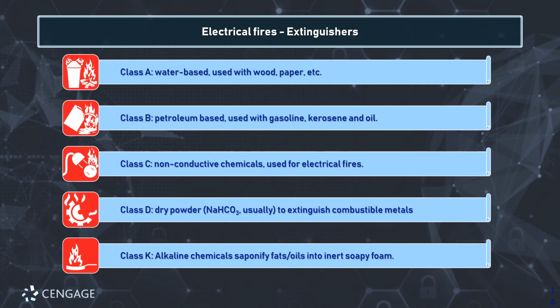And that atomized petroleum then is able to burn much more effectively because there's oxygen mixing all around it. And that's where you get that big ka-woomph fireball thing that you've seen. I'm sure if you look up videos on the internet of water on an oil fire or anything like that, you'll see that it accelerates very aggressively because essentially you've increased the exposed surface area of that particular material.